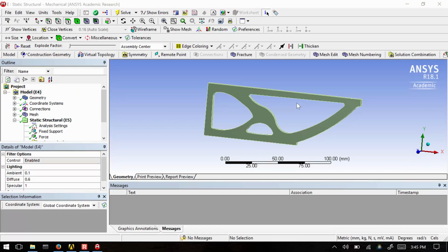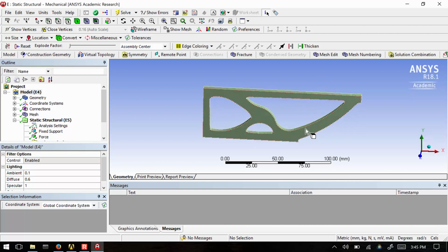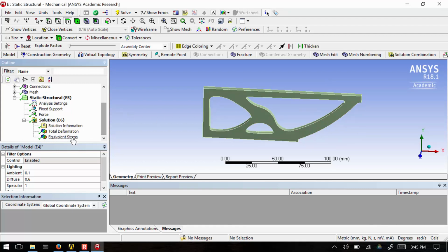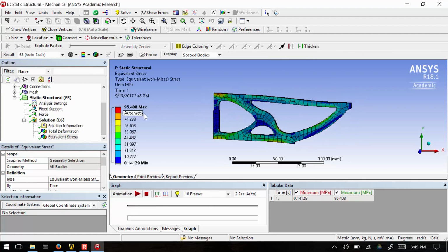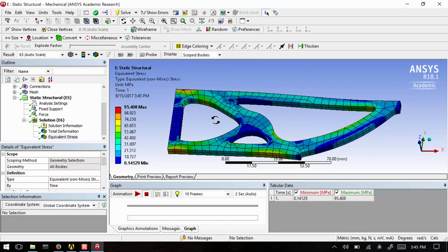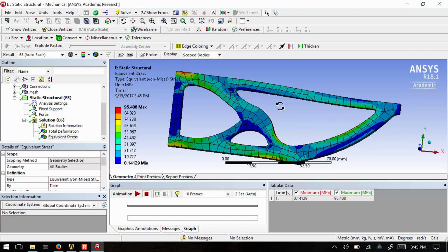So if you go through that process of redoing the geometry with those exact settings I just had, you'll end up with this geometry. After you run the stress, it was 125 before, and I set the maximum to be 100, so now the maximum is under 100. So you can target stress while reducing mass.